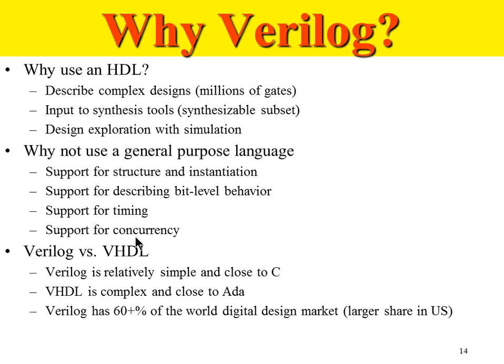Have you seen any board with a crystal on it? Yeah, right? You'll see a small crystal on the board which will generate the clock frequency for your design. That clock frequency is connected to your chip, and your chip works with respect to that clock frequency, internally either stepping it down or stepping it up depending on your requirements. All your timing is with respect to that clock inside the chip. So that's the support for timing aspect.